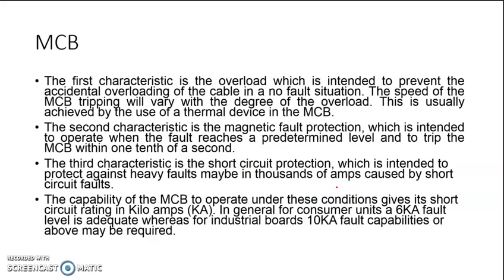So the first characteristic is the overload, which is intended to be provided during the overloading of the cable in a no fault situation. So the MCB will be tripping depending upon the degree of the overload, and this is being achieved using a thermal device in an MCB.